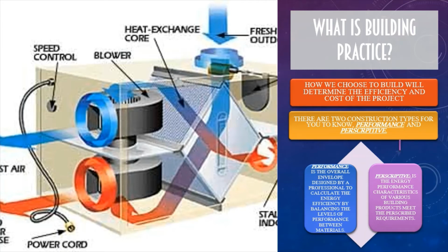When we go through performance, we hire an energy code consultant, where the energy code consultant will do a calculation where they look at all members within the building envelope. So the walls, the roof, floors, and they look at each component like windows, doors, insulation within the walls, and also mechanical devices such as an HRV unit.